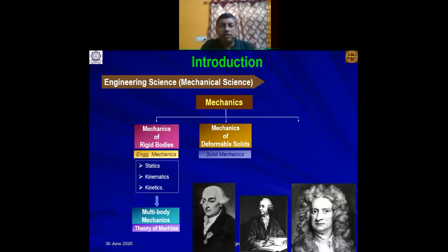So in the sequence for the analysis, first you have to solve either statics or kinetics, depending on whether the body is static or in motion. After solving this, you know the forces acting on an individual component of a mechanism, and you check what will be the internal effect due to this loading pattern, which can be analyzed based on the mechanics of deformable solids.